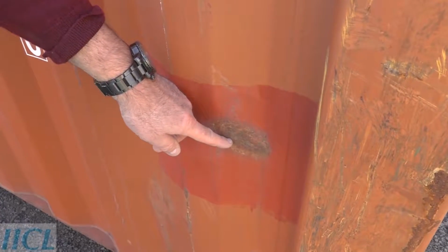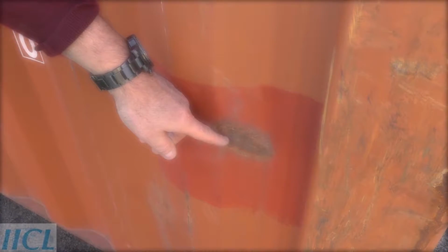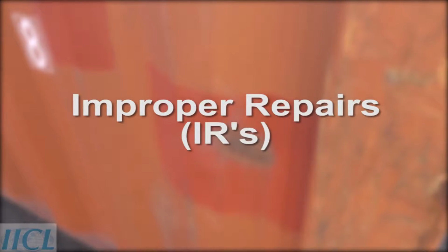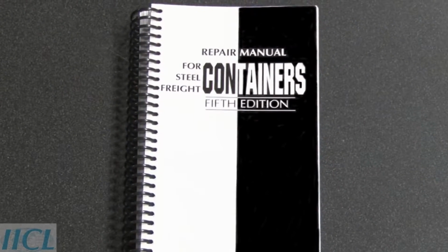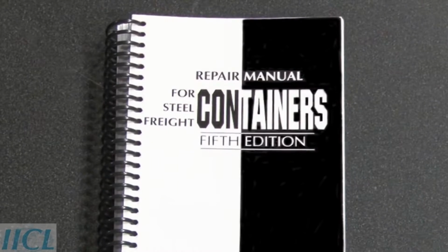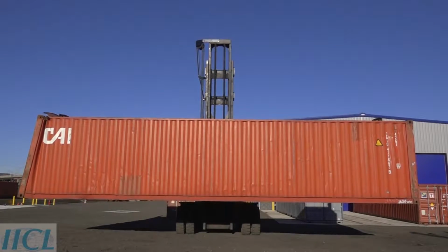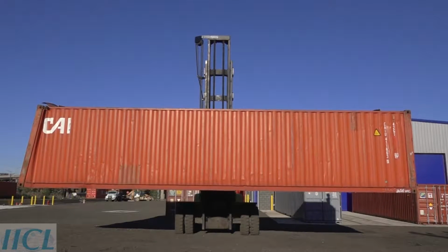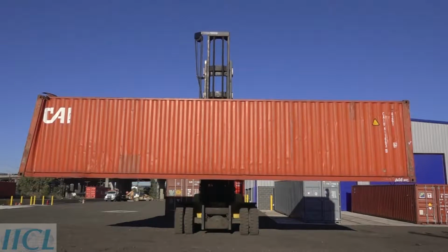When repairs are not made to acceptable technical or quality standards, they're considered to be non-conforming repairs or improper repairs, or IRs. In a future video covering the IICL publication Repair Manual for Steel Freight Containers, 5th edition, repair standards will be covered. Improper repairs are noted here to emphasize that a complete container inspection must not only identify unacceptable damage and wear conditions, but must also check for substandard repairs that have been made to the container in the past.